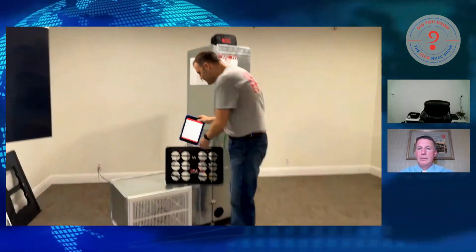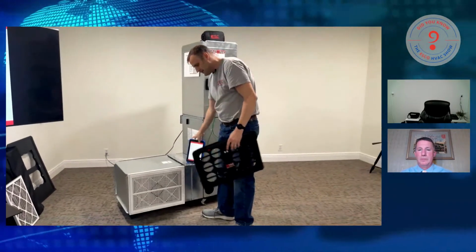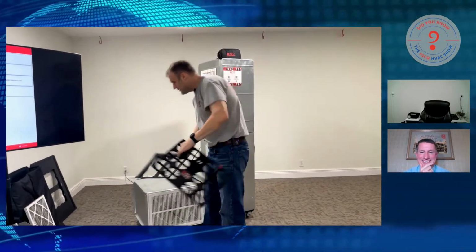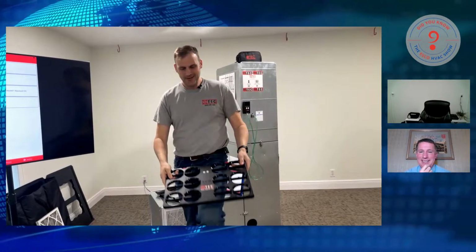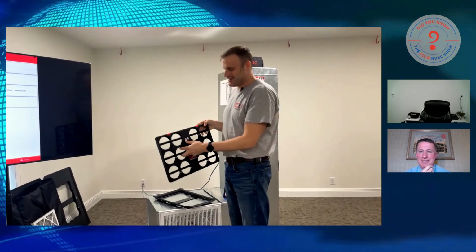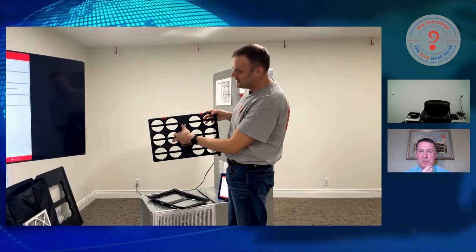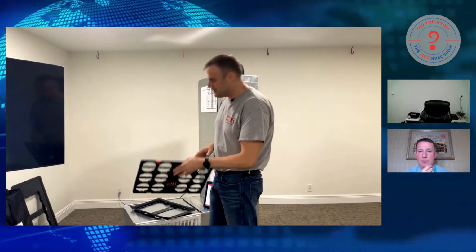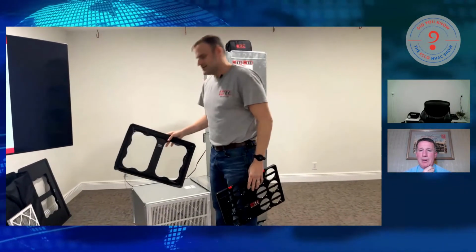Now, let's cover the tools. This is the digital Trueflow Grid. It's an airflow measurement device. It's heavy duty, so if you drop it, more than likely it's not going to break. It's got a power button on the left side. We're going to hold it down until it flashes and then let it go. Once we do that, it's powered up. Is it rechargeable or battery operated? Rechargeable batteries. You'll get about 22 hours of use out of this if you ran it nonstop.